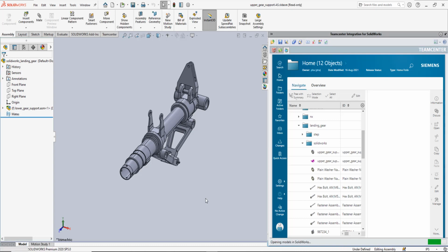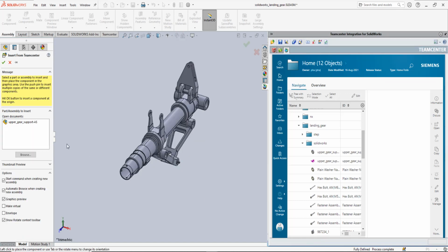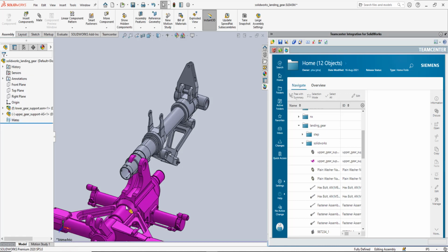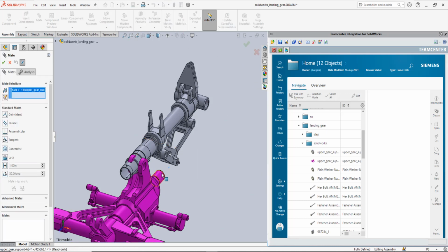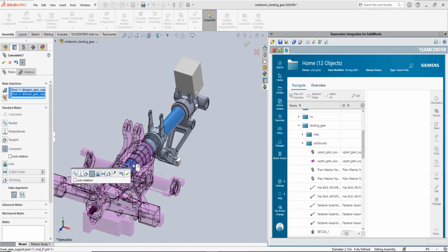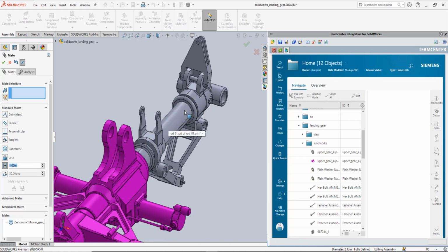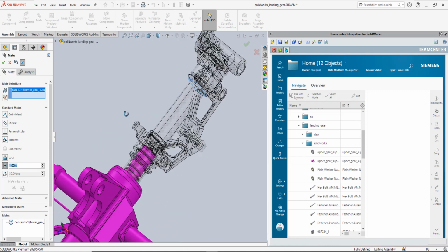In addition to the alignment mate, a dimensional offset is created between a surface on one of the Creo assembly components, and a surface in the native SolidWorks design. Similar constraints can be established against indirectly reused models, but they will not be remembered by SolidWorks the next time the assembly is opened. This is the main advantage of direct reuse over indirect reuse.